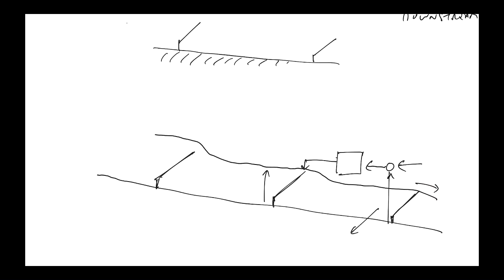Now, of course, the action of the controller here is a disturbance on the upstream pool. By increasing the flow here, that will cause a water level error in this pool, and the controller for that pool will take corrective action by adjusting the flow over its upstream gate. And it's in this way that a change in the flow load down here propagates upstream all the way to the source, resulting in demand-driven release of water from the lake or river upstream.